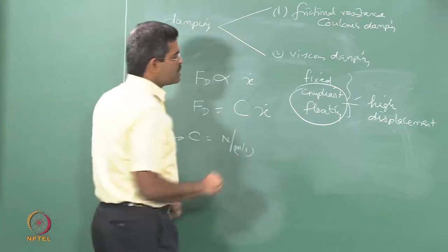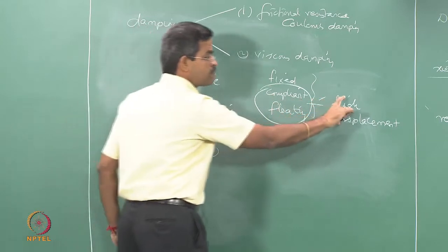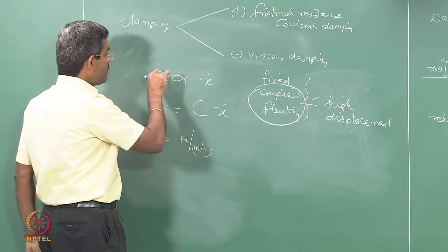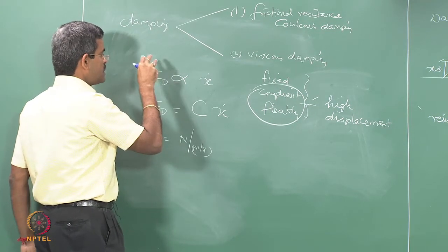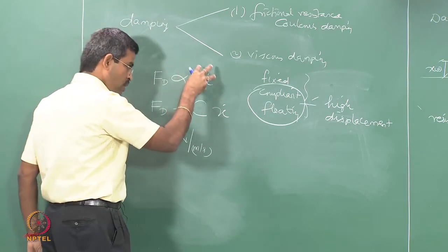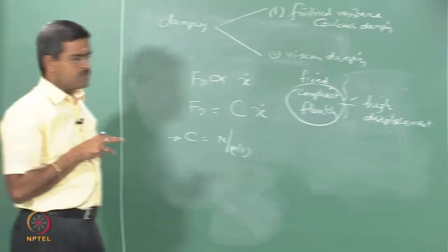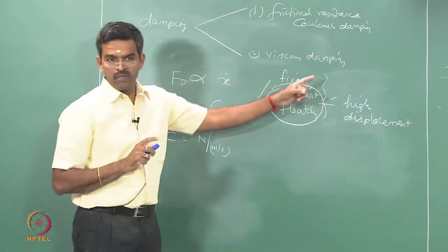So, the one reason is our new generation systems are designed to have high displacement, which results in high velocity. Therefore, the dissipating force, or the decay component of the response, will be significantly present because the velocity of the structure will be significant. So, this qualifies the application of viscous damping in offshore structures.